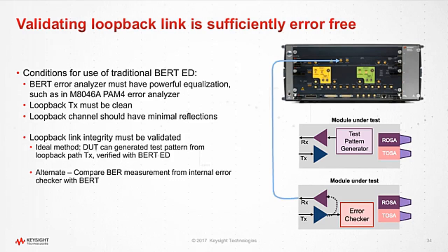So that's the alternative. But in both of these cases, you do need to have some additional hardware built into your DUT. If you're going to be building modules or host chips, it's required by the standards for hosts, but for modules it's not. But you really need to think about this. If you want to measure the BER in the individual parts of the link, you really need to put these additional error checkers and pattern generators into your device when you design the silicon.